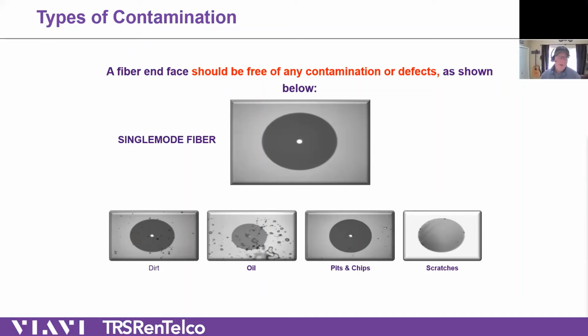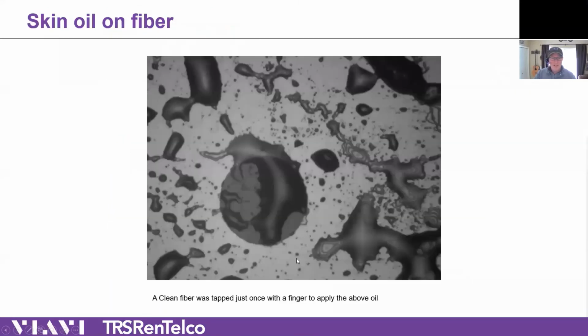And it happens more often than not that you go through the process, you've inspected, you've cleaned, you're holding it in your hand, and somehow your thumb gets too close to it and the oil on your skin pops into it. Super cleanable, as long as you know you did it before you plug it in. And that's a little bit not as black and white as don't plug it in, but when you do see oil in a microscope, it will look like this, right?